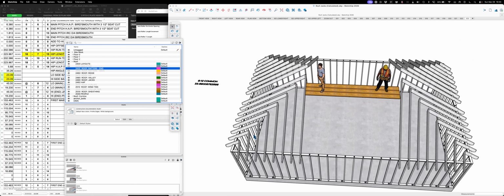But yeah, I like this because all of these on this side are the same as all of these over here, are all the same as over there, and all the same as over here. So you're really cutting 4 of each one of these with this bevel, and then 4 of each one of these with this bevel. And so you could stack them all, and just the guy's got to be smart on, there's a left and right side. As you're looking up at the hip, there's a left side and a right side. And they could sort them out.